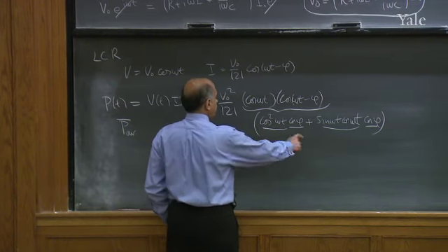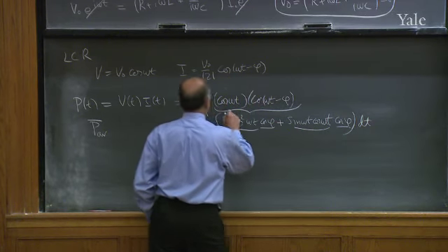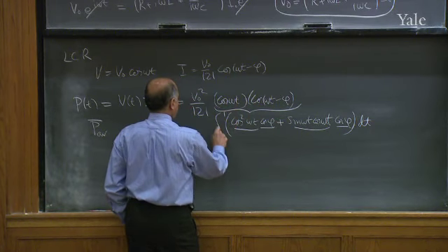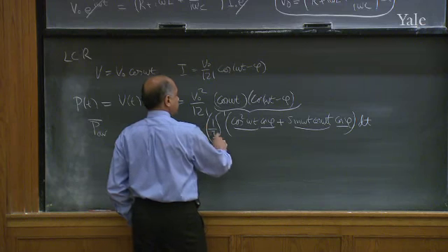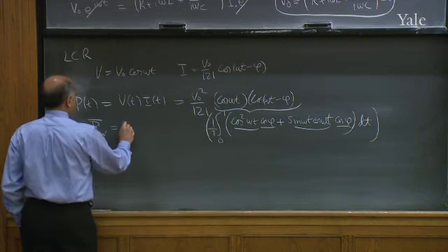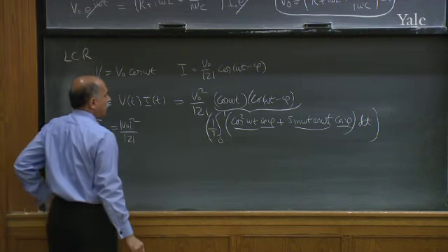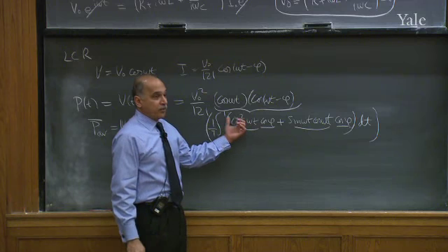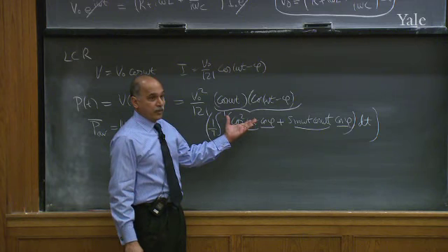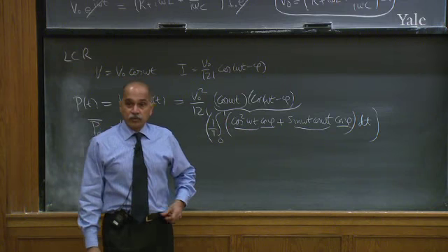That means you take this time-dependent function, you integrate it over time, over a full cycle at frequency omega, and you divide by the time and ask what you get. So let me write the obvious parts, V0 squared over mod Z. Cosine squared is a positive definite number. Its average over a cycle is 1/2. I don't know how you want me to show this.